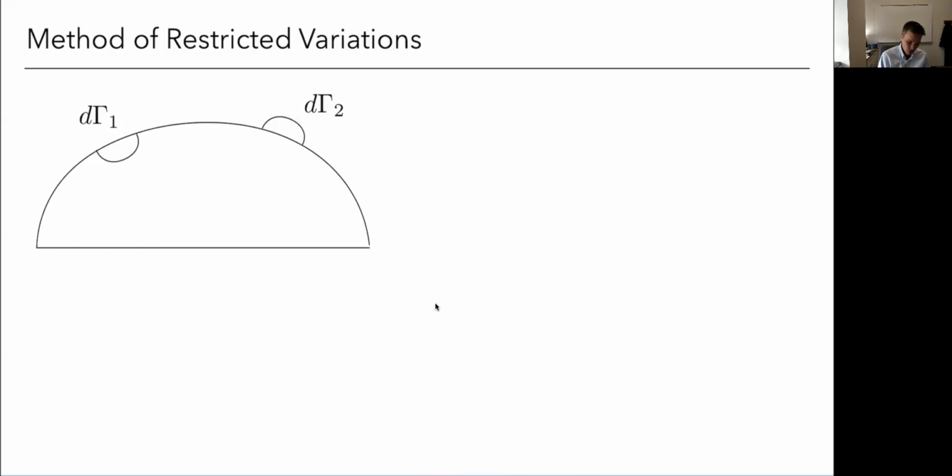Rho, we're going to assume is constant between this station and this station. So to have the change in induced drag to be 0, I just need the downwash 1 times dΓ1 plus the downwash at 2 times dΓ2 to equal 0, right? So I just took the change in drag at the station plus the change in drag at this station according to this formula and set them equal to 0. I could have put a rho in there, right? That would just cancel out.